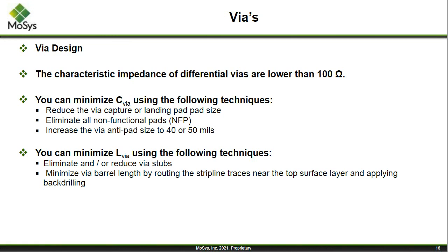The stripline, however, you're going to have to go through a via. You have to go down to those lower layers to get onto the trace, and there's every chance for a discontinuity there. The via impedance tends to drop down to 80, 85 ohms versus the ideal 100 ohm differential that you're trying to keep. So there is a discontinuity that's going to happen, and there are issues of both capacitance and inductance that will change based on how you route.